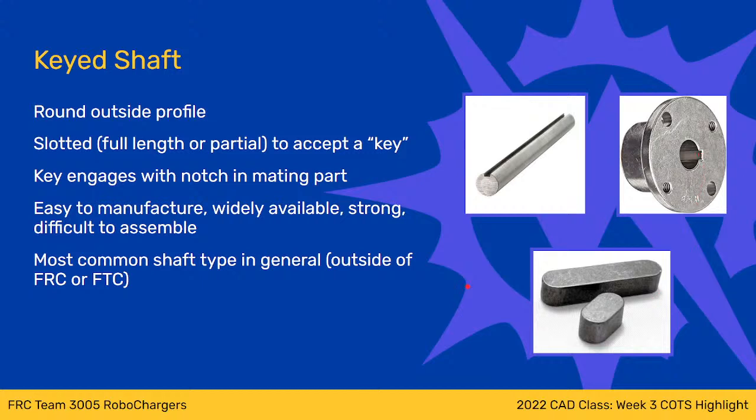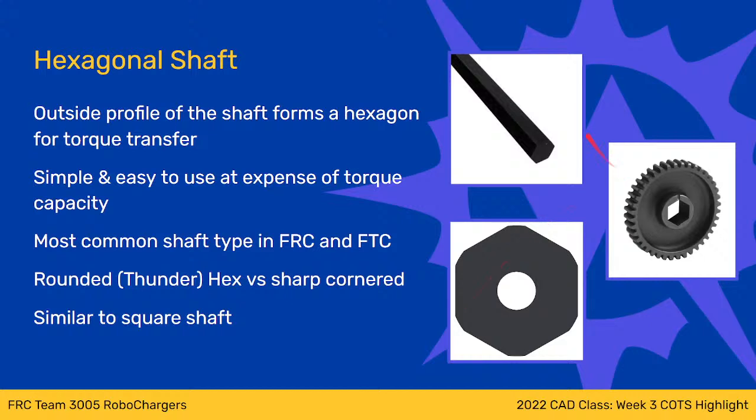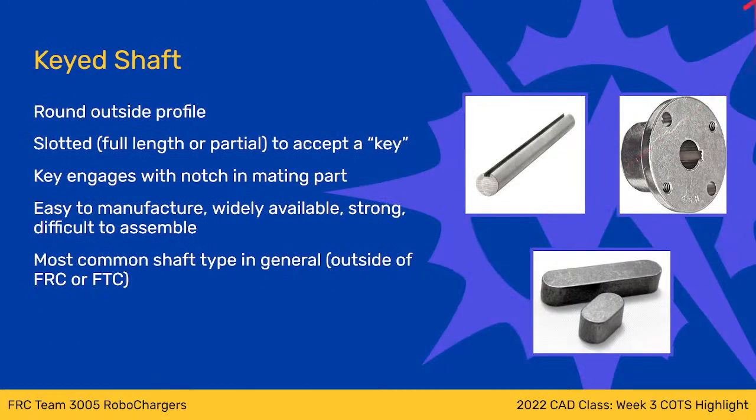And that flat side doesn't produce any mushing, doesn't produce a tendency to damage the shaft. And so basically you have to just straight up shear this key in half in order to fail that torque transfer joint, right? With a hex shaft, you just have to mush the material a little bit. Think about if you ever use a screwdriver where it strips out on a screw, or if you've used an Allen wrench, which is a hexagon in a hex hole, how easy it is for those screws to strip. It's the same thing on a shaft, right? But with a key, you've got this square interface, and so it's much stronger.